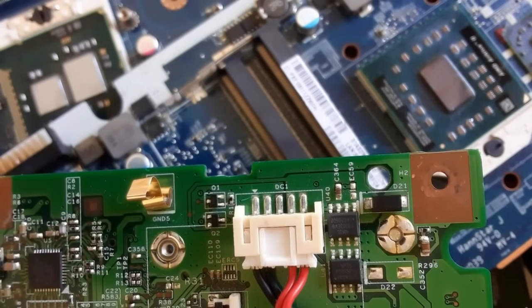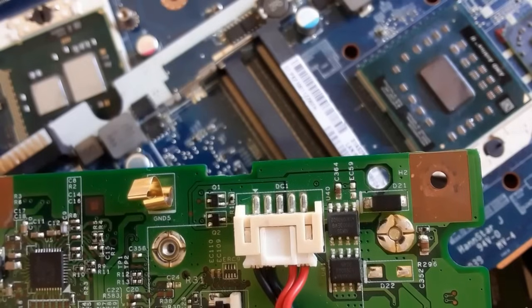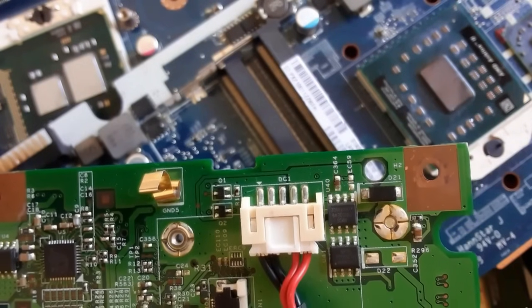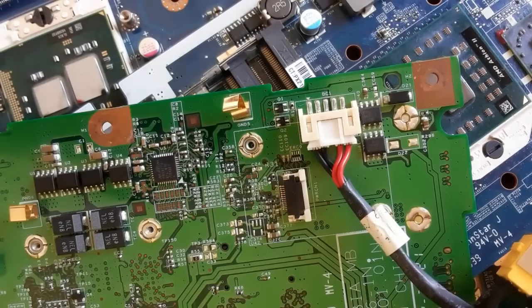Always the anode part is connected to the ground and the cathode, or the negative part, is connected to the power rail. Among the common faults in laptop motherboards is a shorted diode or a bad fuse in the power circuits, near the power jack or the power jack connector.